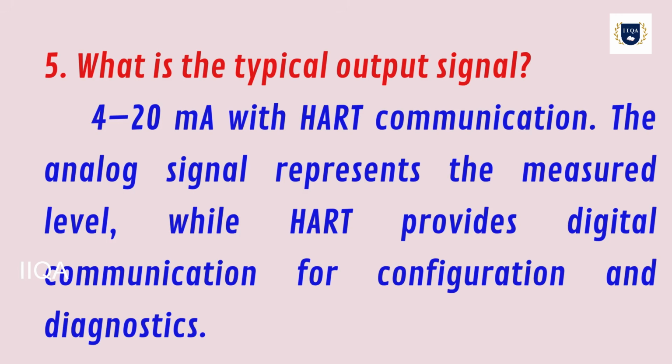What is the typical output signal? 4 to 20 mA with HART communication. The analog signal represents the measured level, while HART provides digital communication for configuration and diagnostics.